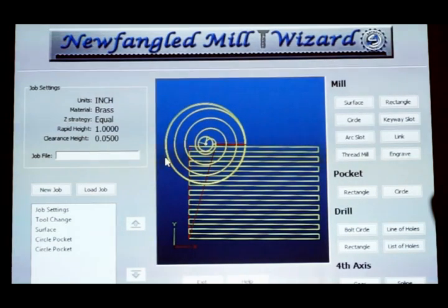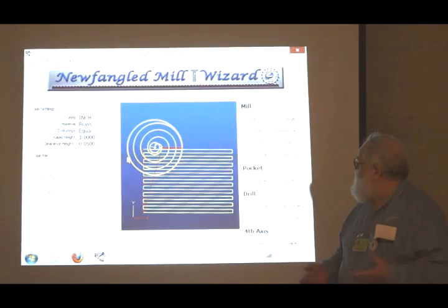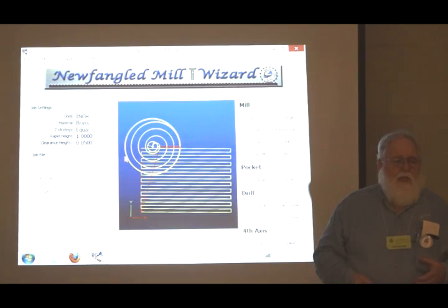All you've got to do is fill in the first screen, go back to the second screen, change the final diameter and the final depth. If you like a step cut, you can leave that alone, but you can quickly make your finish cut. So I was going to do that, but we've changed our mind. I'm not going back and adding finish.